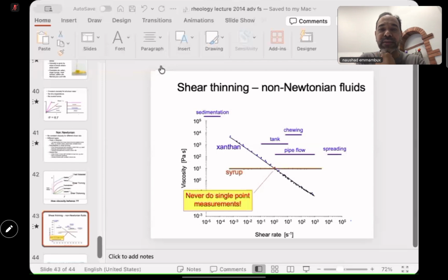For example, there has been a lot of fundamental work done on measuring the viscosity of mayonnaise because it has a lot of oil. As far as I know, you need to use, for example, serrated probes because slip happens. If you use a smooth system, it might not work for mayonnaise because of the slip phenomenon, and you don't measure the shear stress properly.